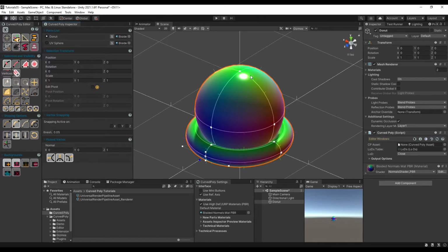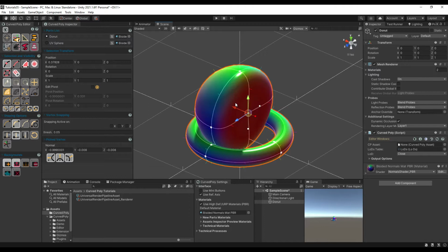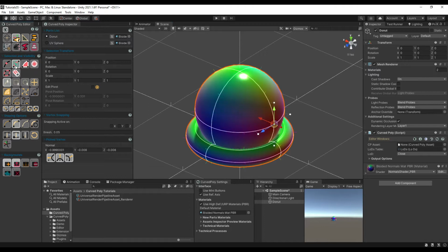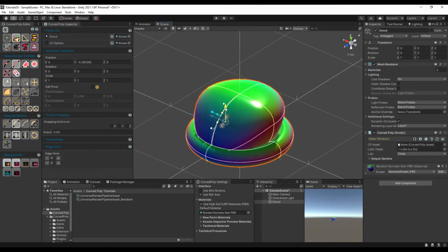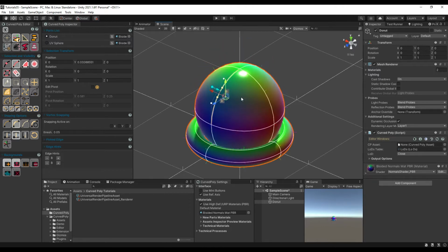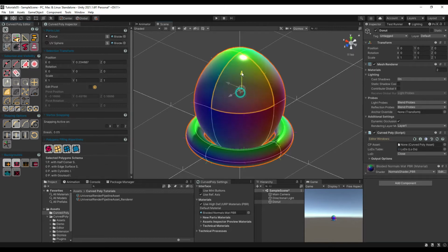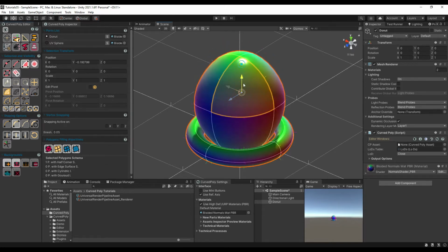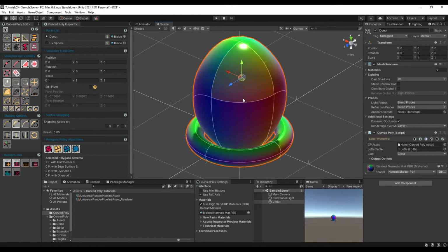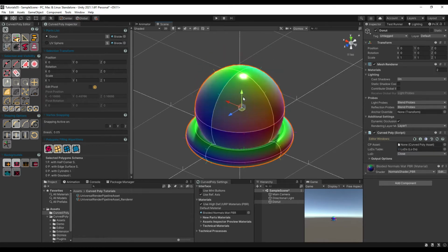With Vertices Selection Mode, you can interact with the vertices of your model. For example, you can click on a single vertex to start reshaping it. Edges Mode is used to select single edges, for instance clicking everywhere on them. Again, once an edge is picked, there are more options to interact with it. Polygons Mode is used to pick curved polygons, again by clicking on the polygon surface. The other options apply to specific groups of elements.